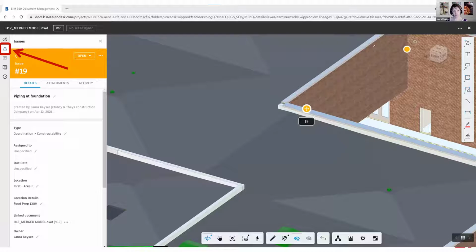So now I'm going to flip. Now I'm in BIM360 document management, the model web viewer. So I go to my issue, and this is what I see. This is why I've created these different viewpoints and screenshots, because it doesn't save any of the sectioning or any of the visibility settings, things that are hidden, transparencies, things like that. But it does actually give all the information.